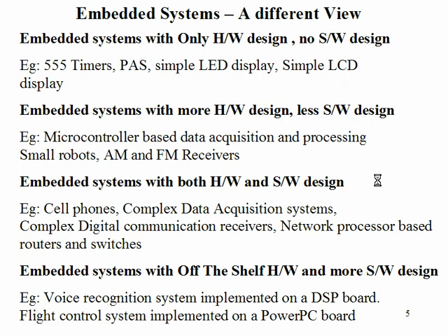Now when you talk about embedded systems with more hardware design and less software design, there are examples like a simple data acquisition system which is based upon a microcontroller. You take data from a thermal sensor, analog to digital converter, through a microcontroller port I read it, I do some processing, I give that information to a computer for displaying onto some GUI, or further I take some action. Let's say the temperature is going beyond some range, then I will try to control another relay.